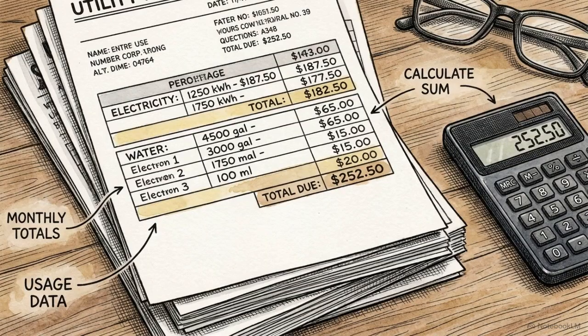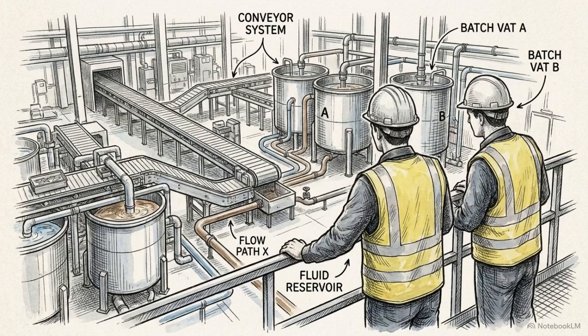Within that scope, the initial phase requires a desktop analysis to verify the accuracy of utility bills and confirm that the purchased energy tariffs actually suit the facility's consumption profile. Step 2 is understanding the process, and it happens before a single piece of hardware touches a pipe.